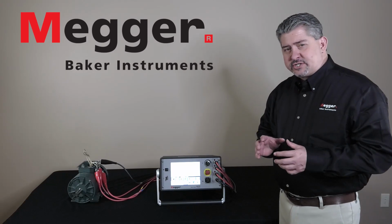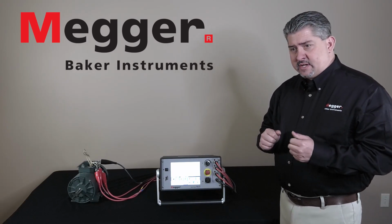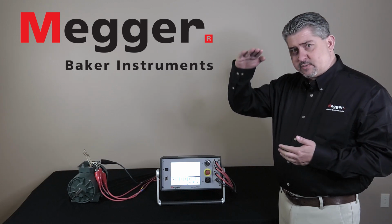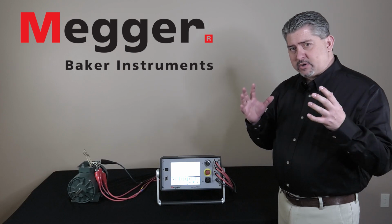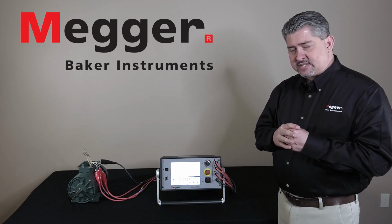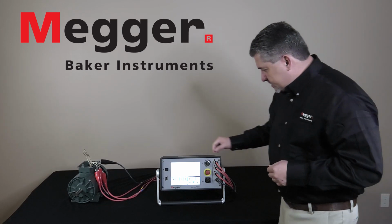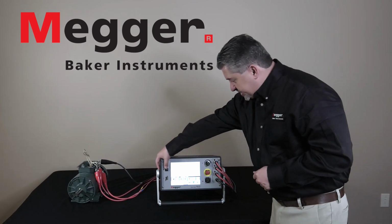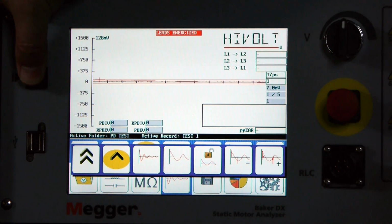The partial discharge test is run very similar to a normal surge test, with the exception that once you get to test voltage, we'll also ramp the voltage down. In that way, we're able to detect when the partial discharge activity ceases to exist, and we'll note the voltage at which that happens as well. To begin the test, we'll push the push to test button, and for the surge, we have to hold that for the entirety of the test.